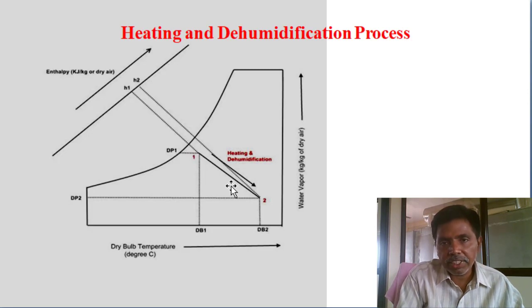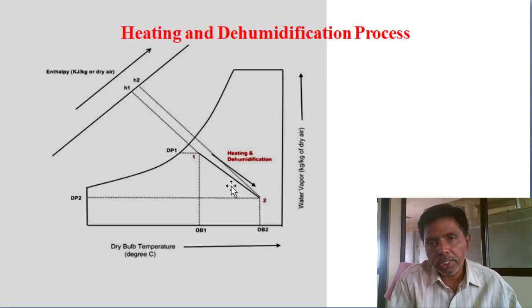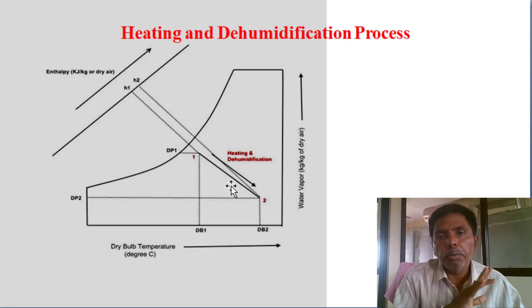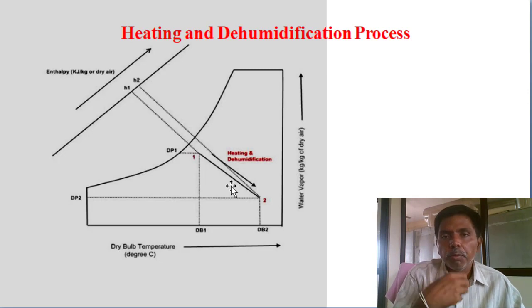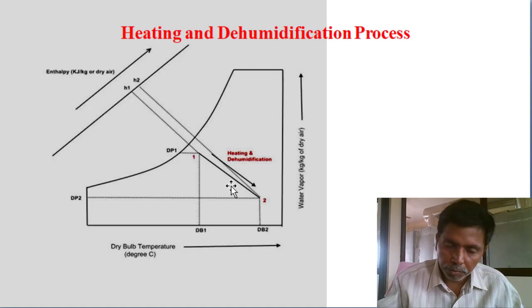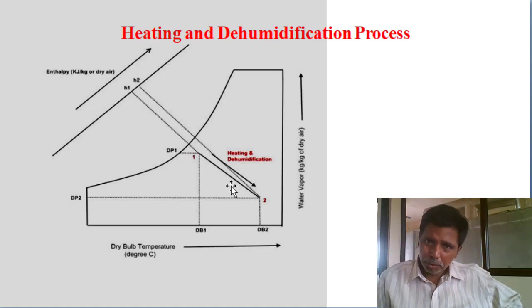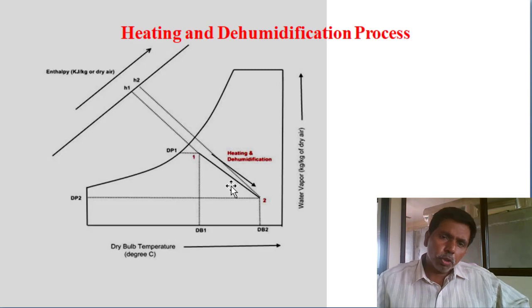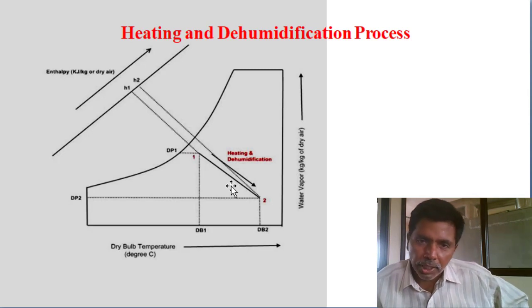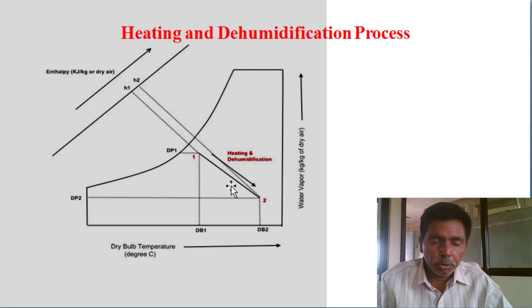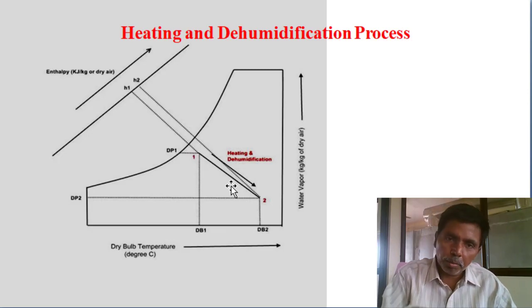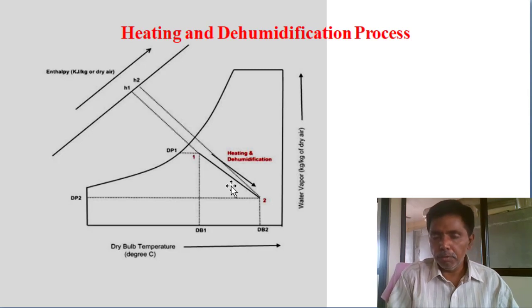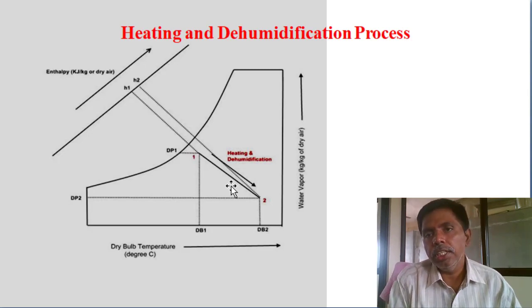Due to this frictional operation, temperature will rise and it will remove the moisture, but after some time it will reach saturation condition. At that time we want to replace the disc, and this disc we want to heat up to 150 degrees. If silica gel means 150, Al2O3 means more than 200 degrees. We are heating, so desorption will take place, and the same disc we can use for operation again. Based on the air moisture content, the number of discs are required. Every time you want to change the disc.